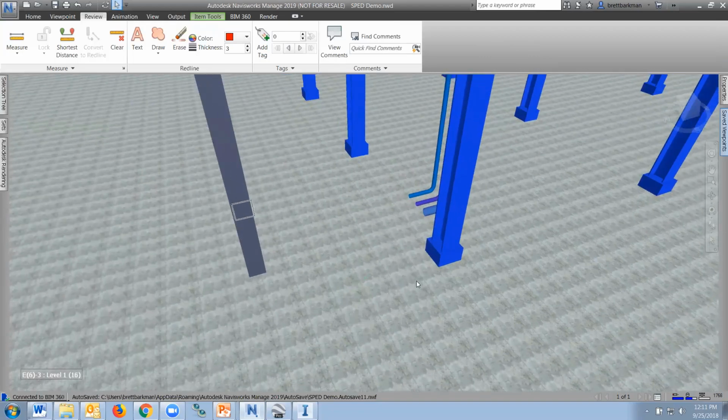Thanks, appreciate that. Okay, so first thing I want to do before we start this move is select my objects again. So I'm going to select both those files. Then what you'll do is go over to the Review tab, because in the Navisworks model, I don't yet know how far things are from each other. So I'm going to go to Review and do a point-to-point measure.